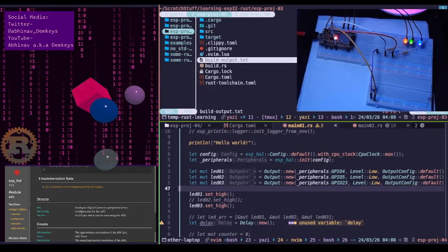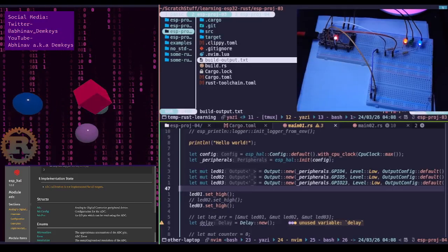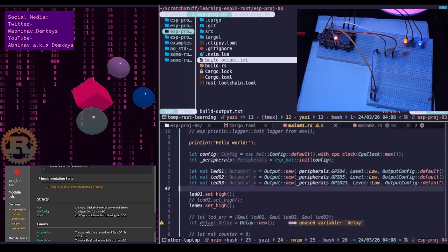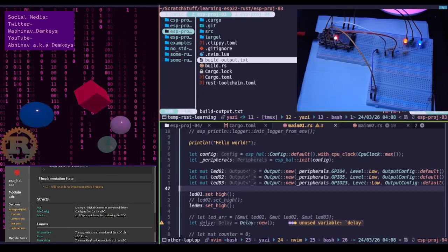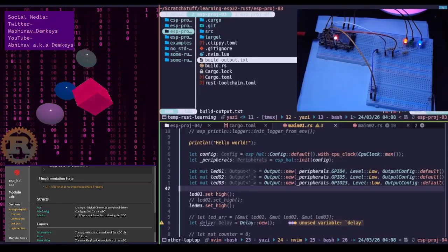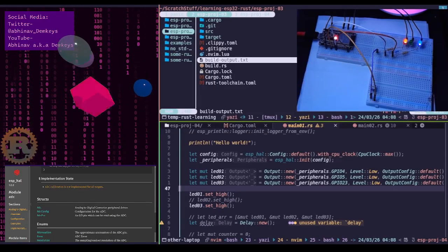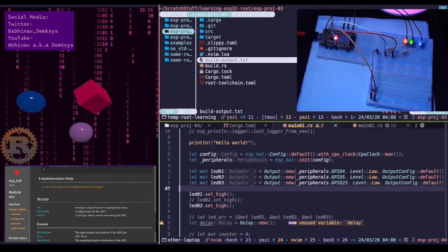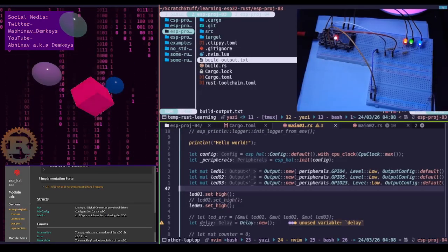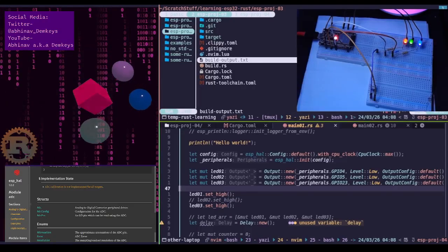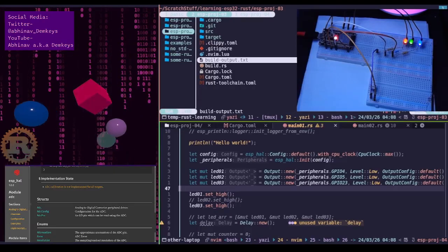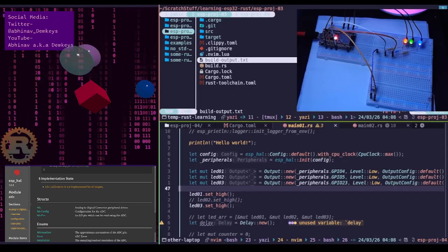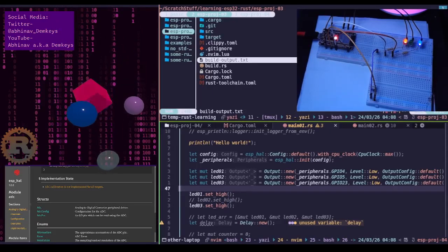Okay, how you quote unquote calibrate with this formula. Since the ESP32 doesn't do this for you in no STD yet, you can create your own quote unquote map using a multimeter and two data points. Point A, you connect the pin to ground and then read the ADC. Let's say it returns 42.